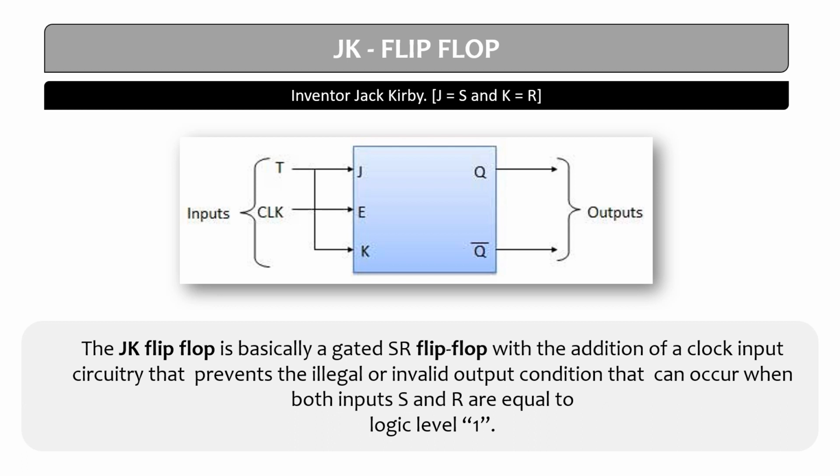So here please keep in mind that the connection between the outputs and the inputs to the AND gates determines the input conditions to R and S when J is equal to K is equal to 1. When J and K both are 1, at that time we need to check this. Fine.